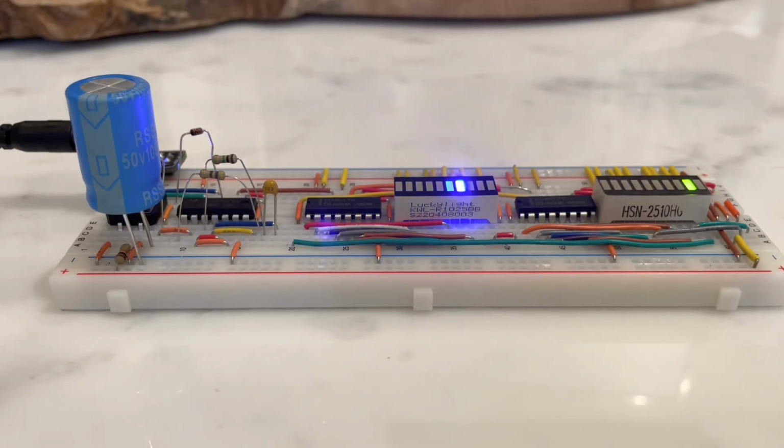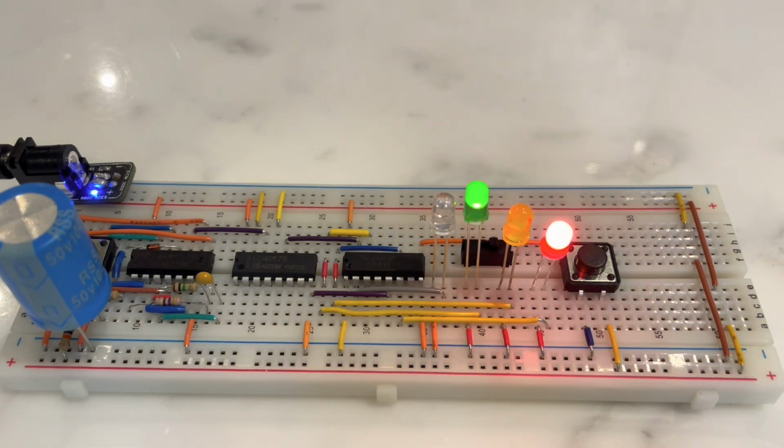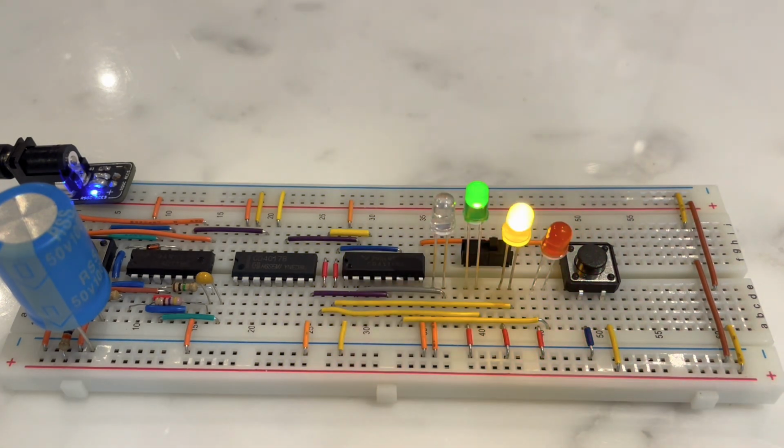As we see here, the circuit is counting how many flashes are coming through by applying them to a bar graph. This is possible due to the pin configurations on the 4017. Now, moving on to the decimal up-down counter. The purpose of the circuit is to demonstrate how circuits can count in binary number systems by incorporating a 4510 IC and 4 LEDs. Instead of counting in decimal, the 4510 counts in binary code.